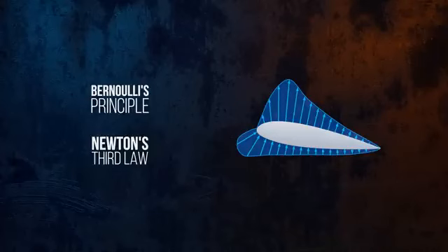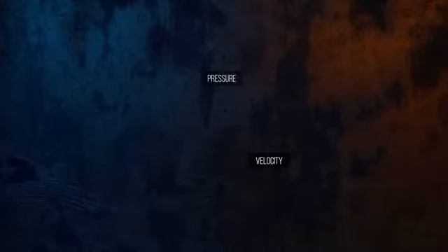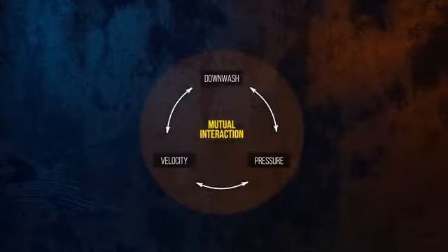The problem is that there isn't always a clear cause and effect relationship between the different phenomena which are involved in generating lift. Whether we're talking about the fluid velocity, the pressure distribution around the airfoil, or the downturning of the fluid, in reality, all of these things are happening simultaneously and are mutually interacting. Nevertheless, these explanations are useful and can lead to a more intuitive understanding of lift. We can easily imagine, for example, that increasing the camber of an airfoil will allow it to deflect a larger amount of fluid, and so will increase the lift force.